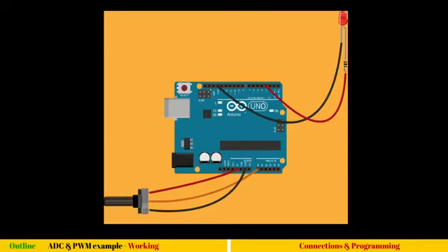So the potentiometer is 10 kilo ohm, and from end to end it measures 10 kilo ohm resistance. So when we connect end to end to 5 volts and ground, you can interchange these probes, it doesn't matter. So end to end voltage will be 5 volts, and while changing this knob, the center point which is connected to the knob will change this resistance, and you get a different resistance at every turn.